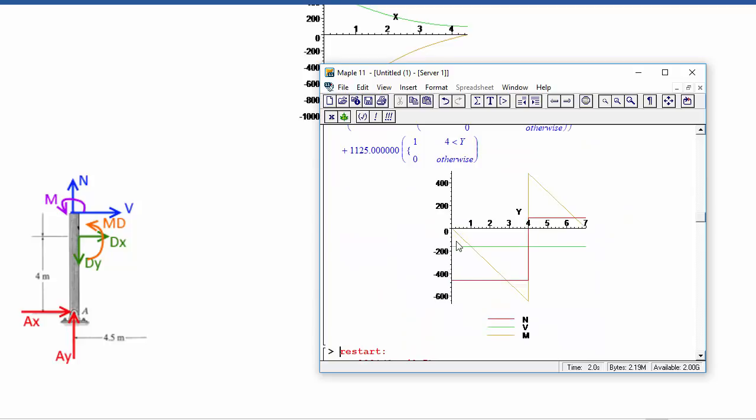So we've got a moment that's 0 at the bottom. And then after we pass that 0.4, then the moment has to increase a lot to counteract this md. Now you think, okay, wait, after md gets added, then wouldn't this have to decrease to keep the whole thing in equilibrium? Well, no, because md ended up being this big negative number. So the moment that's applied from D is actually in the opposite direction to what's shown here.